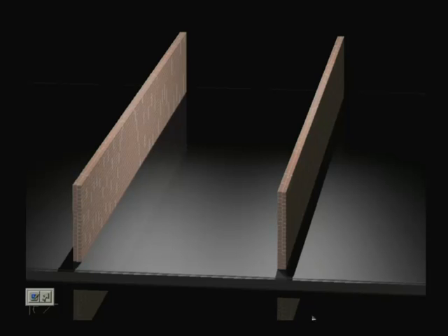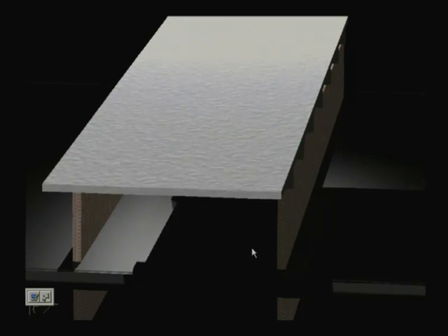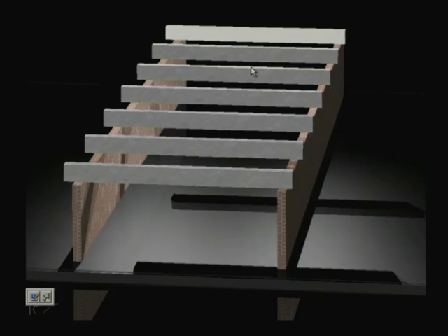Just review it. So, we have two brick walls, we can take this one say 250 millimeter width. Just for clarification we have made it like this, there are so many beams at 3 meter spacing, covered by the roof or slab. These are the different beams, but we have constructed these beams integrally with the slab. So, we can take the action of T beam.